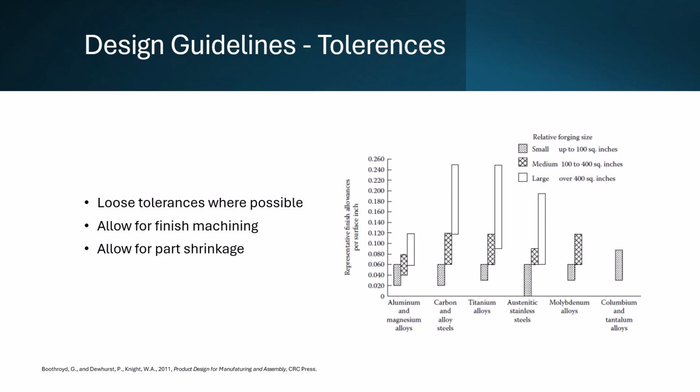Machining allowances should be added in to permit machining on mating surfaces or parts requiring precise surface finish. These surfaces should be built up so that the material removal doesn't drive the part out of tolerance. Additional machining may be needed on flash and web geometry or oxidized surfaces and should be added into the machining allowances.